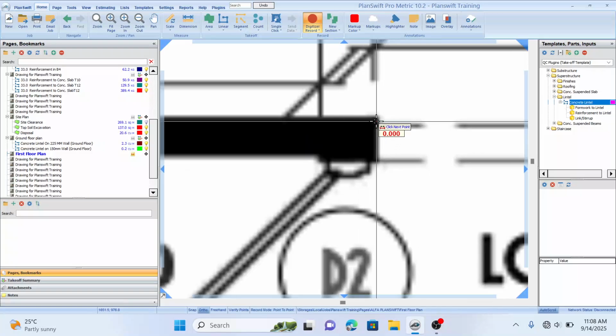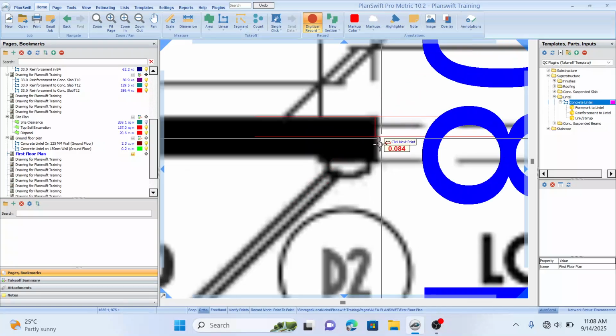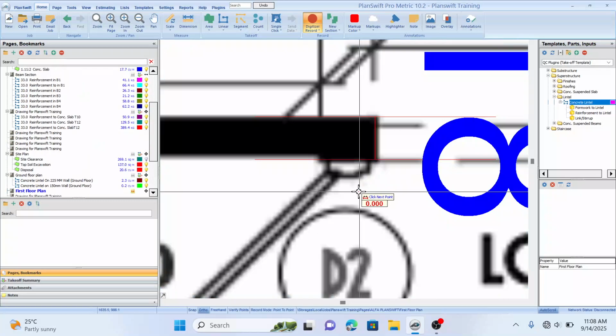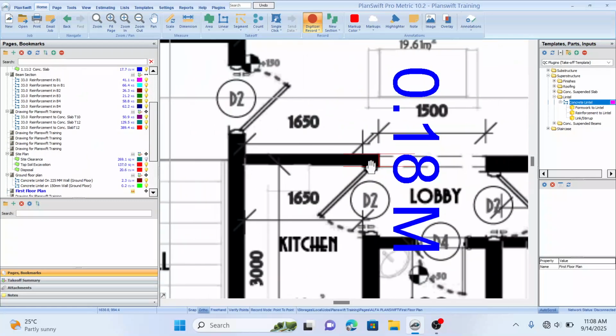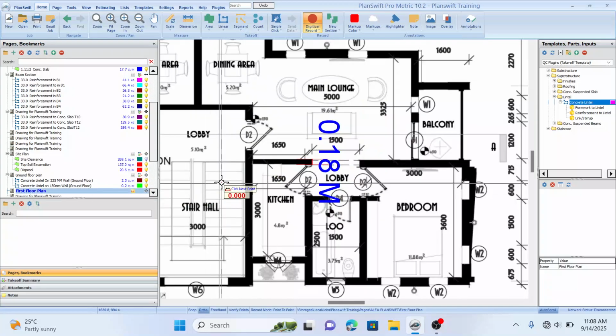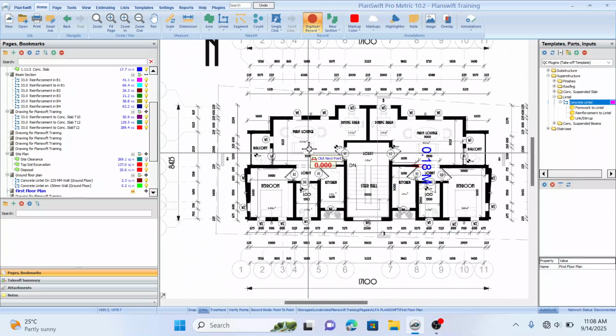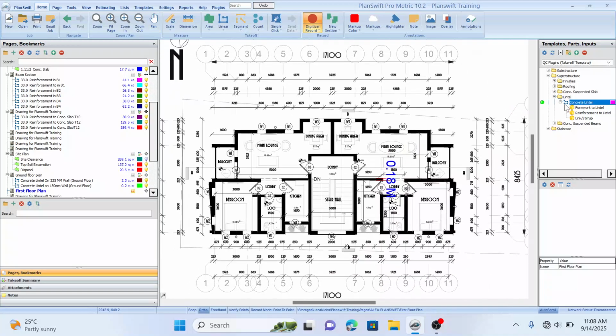This particular wall looks like 150 wall. I think it's the 150 wall, because mere looking at this, it is smaller than this, and this particular wall is smaller than this and this. So we have 150 wall here too. So our lintel will be divided into two.